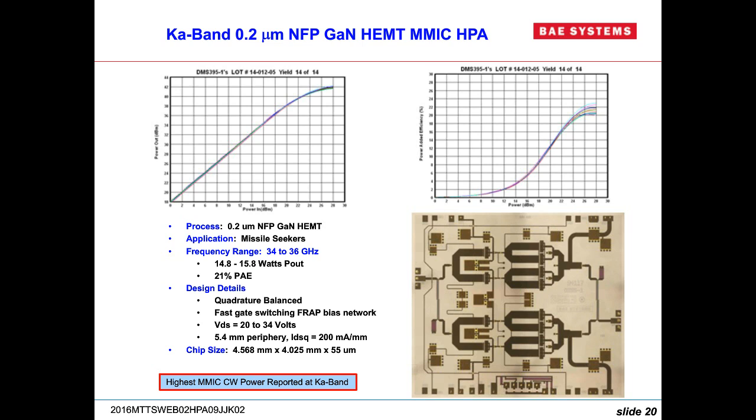For many applications, GaN on silicon might actually be a better choice than silicon LDMOS, where you want to pay a little bit more for performance, but you don't want to go the full Monty and get to a silicon carbide GaN device. So it's a spectrum out there. You'll find everything where there's a market. You'll find parts that are out there, and there are vendors that do GaN on silicon.